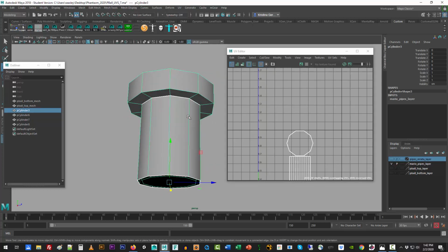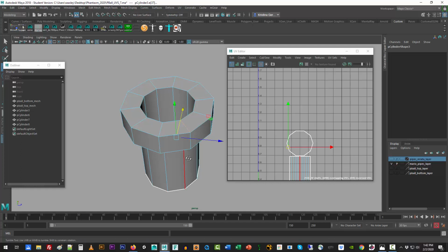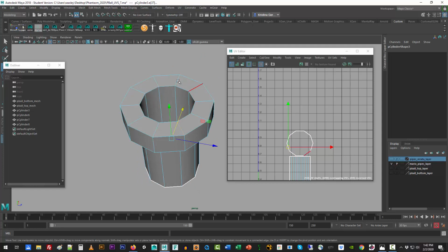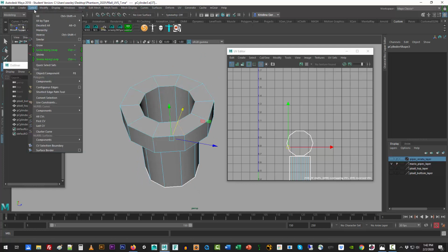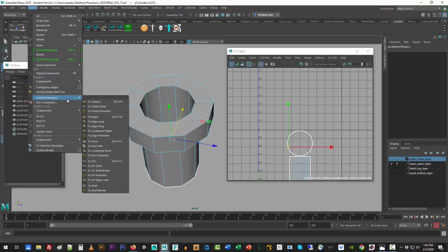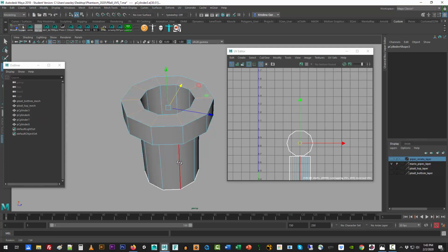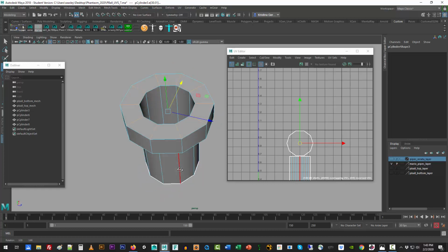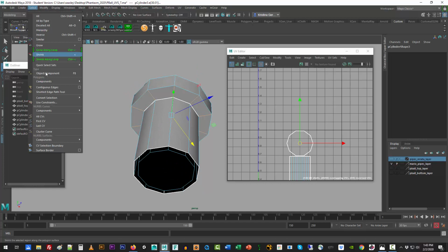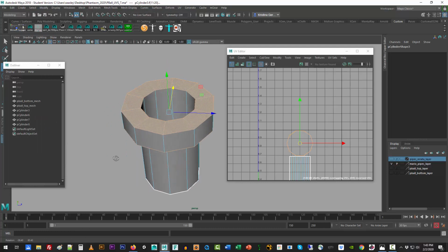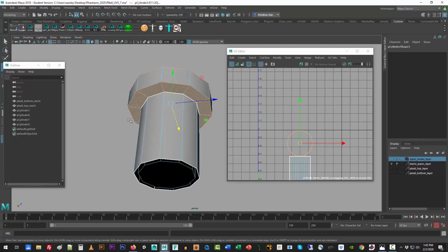So the first thing we're going to do is to grab the edge on the bottom, any edge on the bottom and the top that has this little phalange, and this edge, this lip as well. And then using our trick of coming up here to convert the selection to edge ring, we did that earlier. Let's grab all these rings here on what constitutes kind of the two wheels, and then convert the selection to faces. And that allows us to project downward at once.